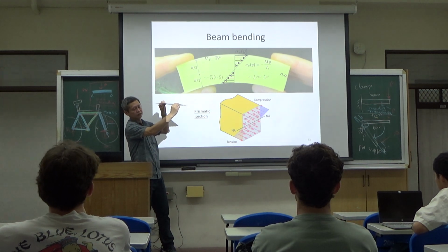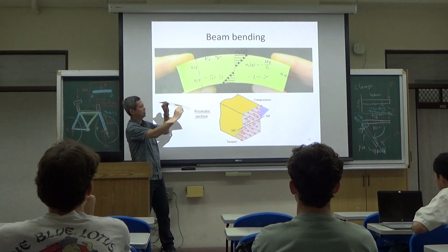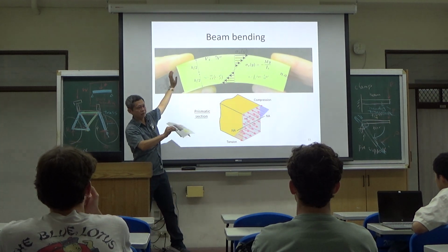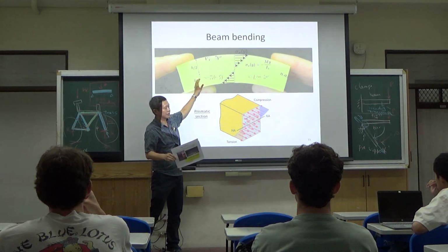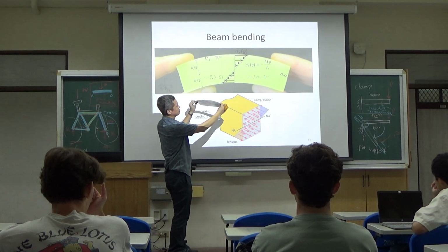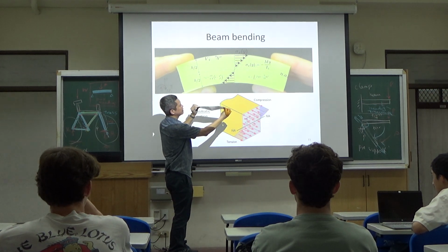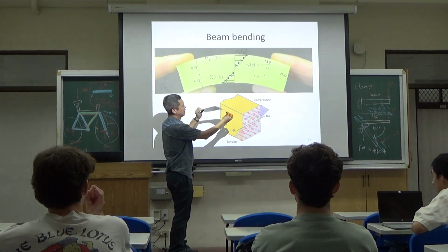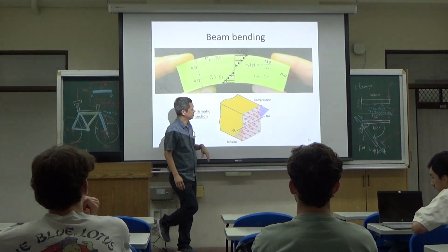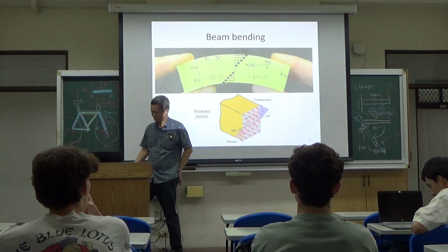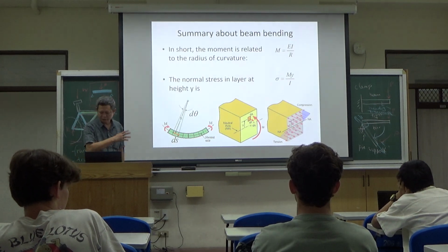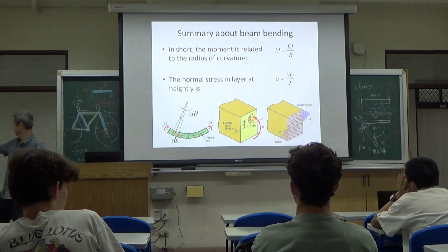If you now cover the layers all along and you start doing the bending, you will find that the top layer is going to undergo tension, and then the bottom layer is going to undergo compression. Can you see clearly? This might not be clear enough. The one under compression, if it is separated, will be buckled. So let's analyze the structure. Let me try to draw it out so that you have a clear idea.